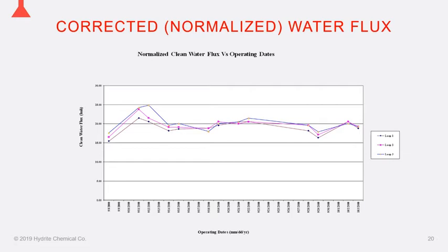We could have had a fines saver screen get a bunch of cheese fines in the system, or a separator malfunction and release a bunch of fat to the system. And that could have caused some lower fluxes, and then you can see that it slowly recovered. But anyway, that's what a normalized flux graph looks like. And that way we can compare to see what the health of the system is. And this one looks pretty good.